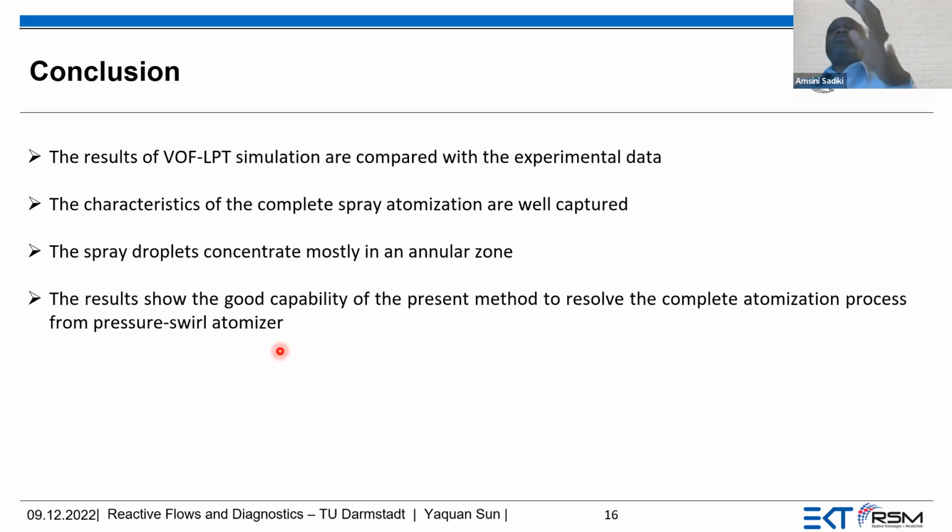And the next step is now to couple it to combustion modeling. And at this point, we will include the stochastic field, Eulerian stochastic field, to account for the turbulence chemistry interaction, and then we will use naturally tabulated chemistry for that. It is NF10. We have already tabulated chemistry for that. We have only to update the operating conditions. And this is our next step in the next month.